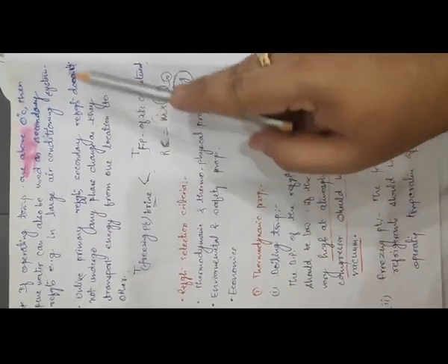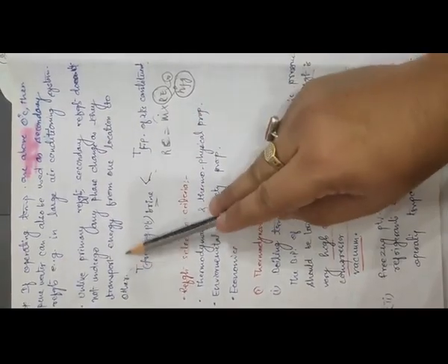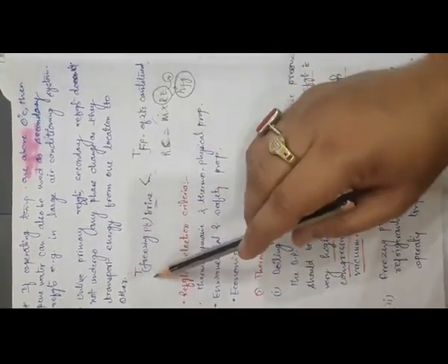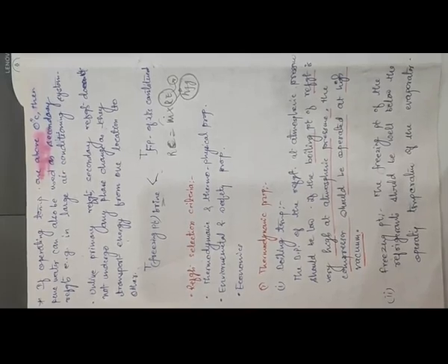Unlike a primary refrigerant, a secondary refrigerant does not undergo any phase change as it transports energy from one location to another. It means the basic difference between a primary refrigerant and a secondary refrigerant is that the primary refrigerant undergoes a phase change during the evaporation, condensation or absorption process, while a secondary refrigerant does not undergo any kind of phase change while it transports energy from one place to another.